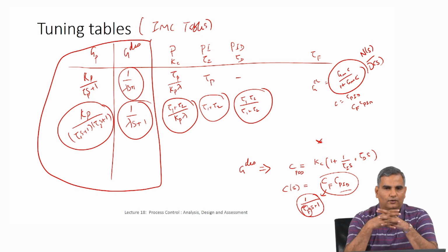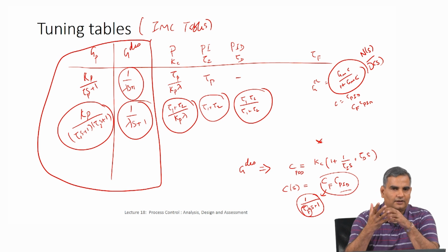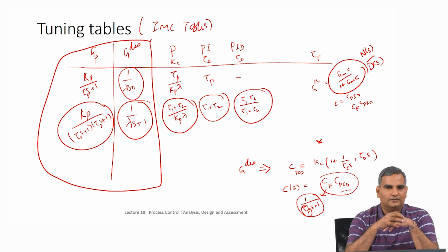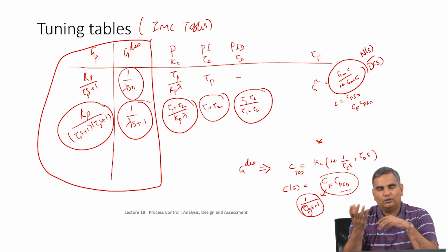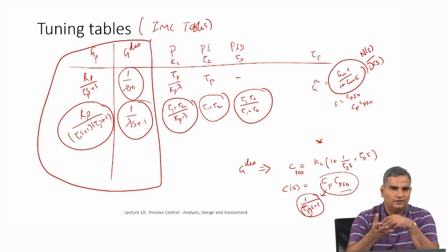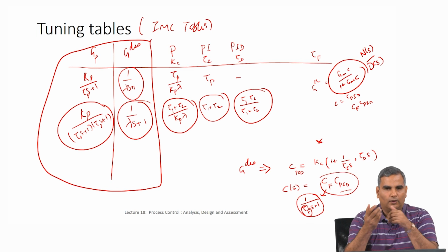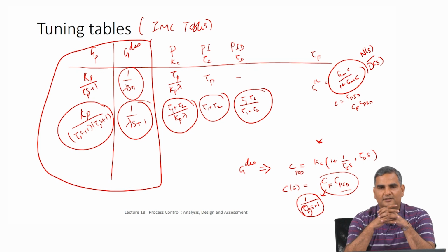However, if I have these coefficients also as functions of the controller parameters, then we want to know what happens to the stability of the system, and without knowing the controller parameters we cannot actually get the roots. So we came up with this Routh stability table where remarkably you can actually make decisions about whether there are any roots on the right half plane without ever computing the roots.